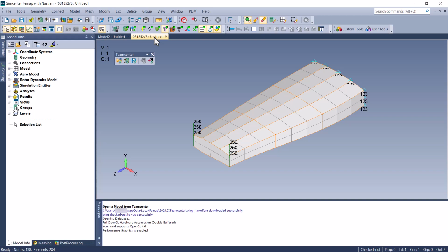When a model is not checked to be opened as read-only, Simcenter FEMAP attempts to check out the data in Teamcenter during open operation. Data Checkout provides us an exclusive access to update the data on Teamcenter. We can see the status of model checkout in the status bar. Hover over to see a brief explanation.